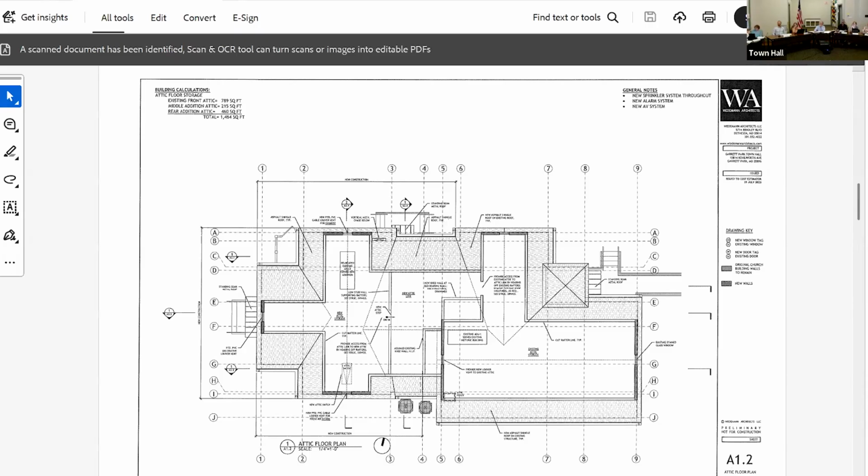The other thing we are planning to do, we presented to the Historic Preservation Commission what they wanted to hear, which was that we would preserve as much of the historic fabric on the outside of this building as possible. Unfortunately, you can tell that a lot of it is in very poor condition. In all likelihood, part of that has to do with the way the wall was built and the inability of the siding to breathe behind it. So for the purpose of the cost estimate only, we've instructed, the Historic Preservation Commission accepts replacement in kind if salvaging the material is not possible. We're going to take the worst case and we're going to replace it all.